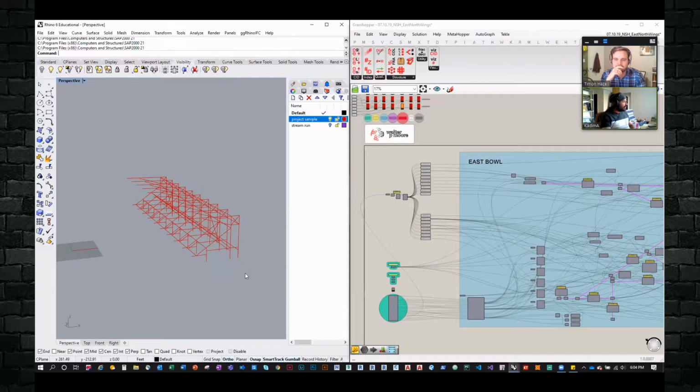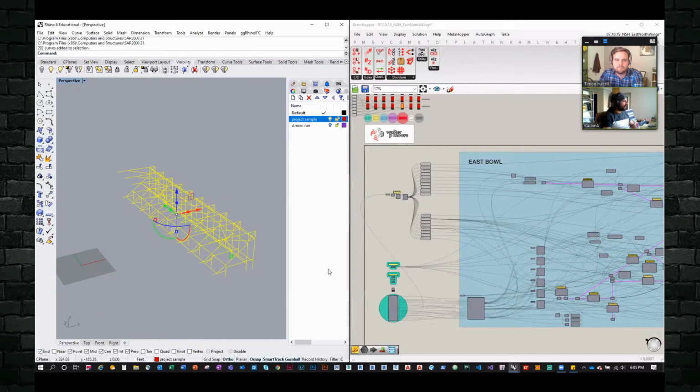One way to optimize workflows is to develop some sort of script that could flex based on design changes from our clients. So, diving into Grasshopper and just working and reworking bits of scripts, eventually that developed into this set of clusters that helped me build a stadium structure. What you see on my screen right now is just an east wing of one stadium that I completed. And this entire thing was simply automated through a Grasshopper script.